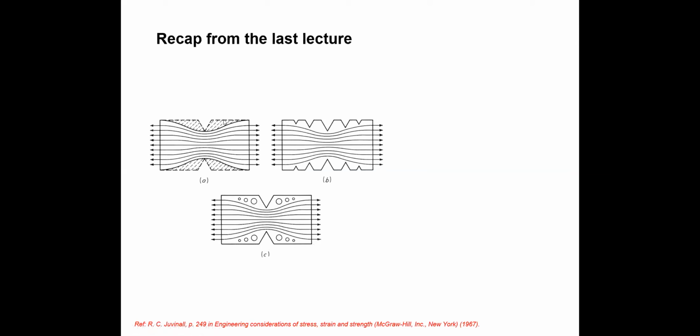Around the stress raiser area, there is a stress profile you can see. Due to that, you can remove the material if you want, because this is unnecessary material. But you can use that area to strengthen the element. You can use this kind of additional stress raisers to distribute the stress. It will dilute the stress around this area, and then the maximum stress will be lower than here.